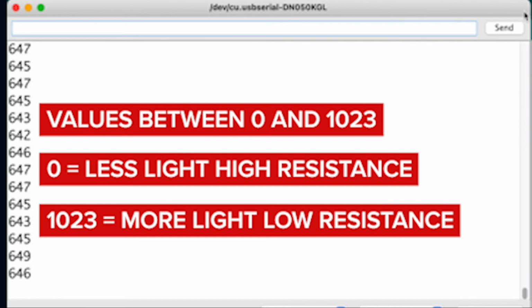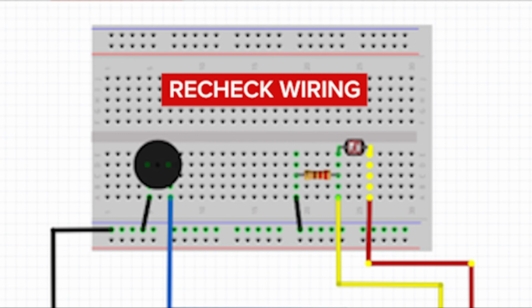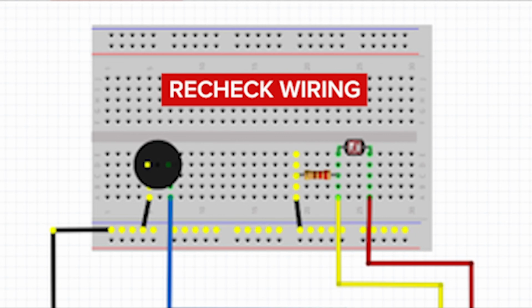If your Piezo Buzzer is not emitting a sound, don't worry. Recheck your wires to make sure your jumper cables are aligned with the positive and negative legs of your Piezo Buzzer. Also ensure that your light sensor is connected properly to the resistor.